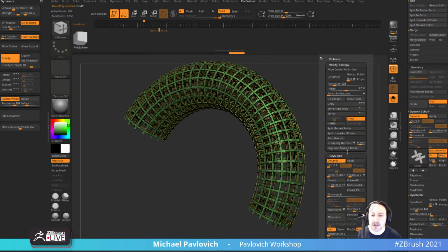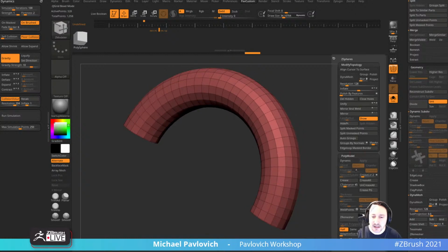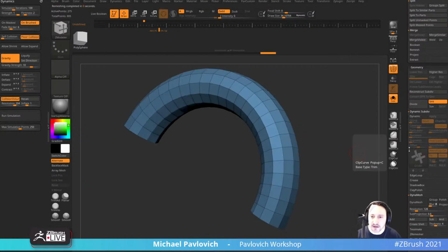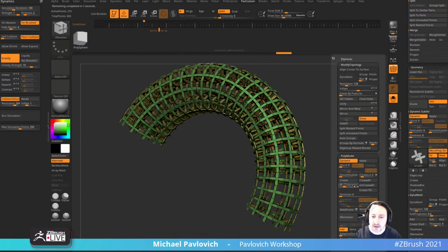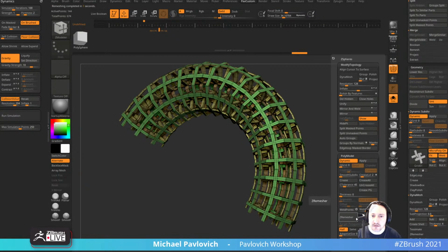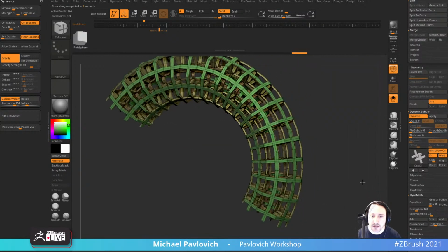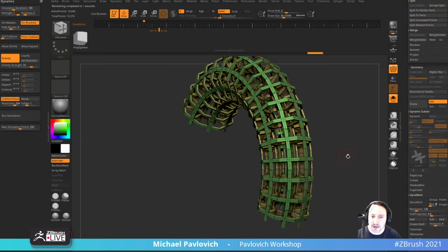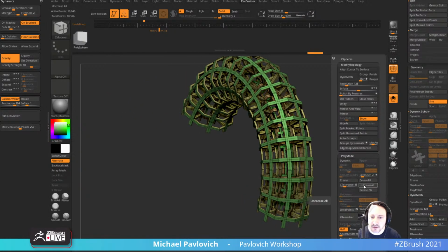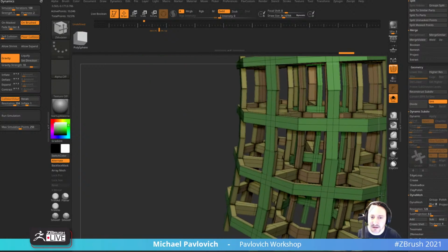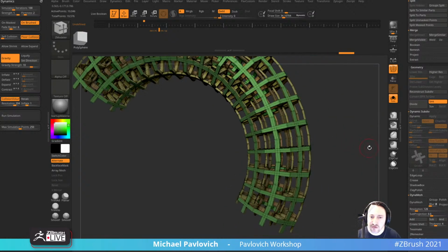And if this is too much, you're like, I don't need that many, this is just, again, ZRemesher half, and that'll give you fewer, and then turn dynamic back on, ZRemesher half, and then it'll give you fewer. So there we go. Yeah, that seems fine. So let's go ahead and say dynamic apply, and then let's do uncrease all, and then we'll run another crease tolerance. Is it grabbing everything? No, it should be okay.